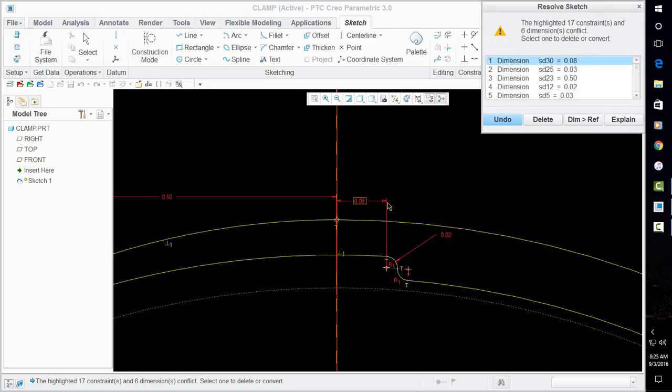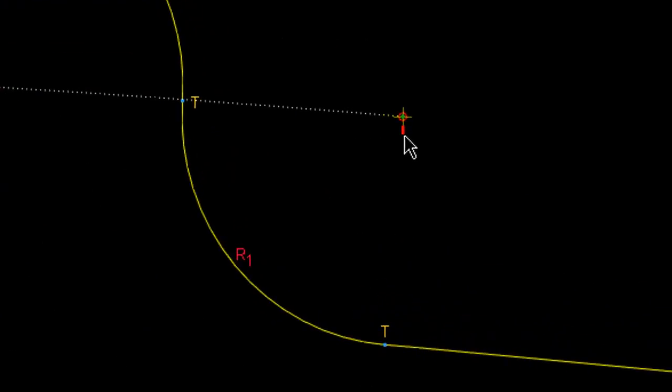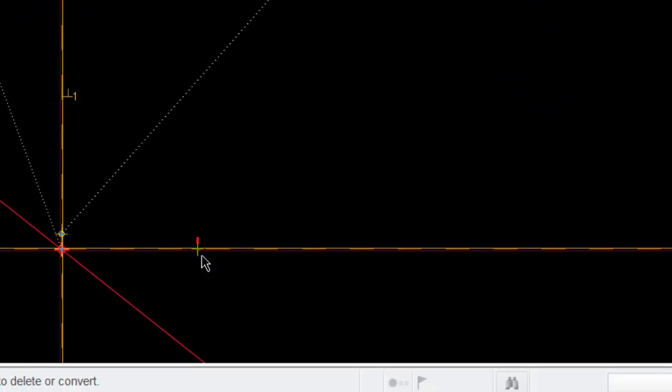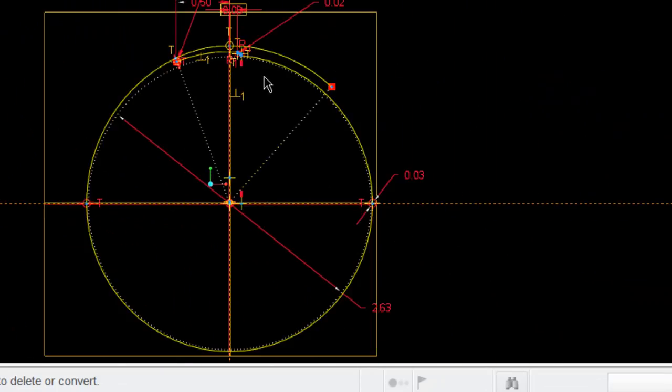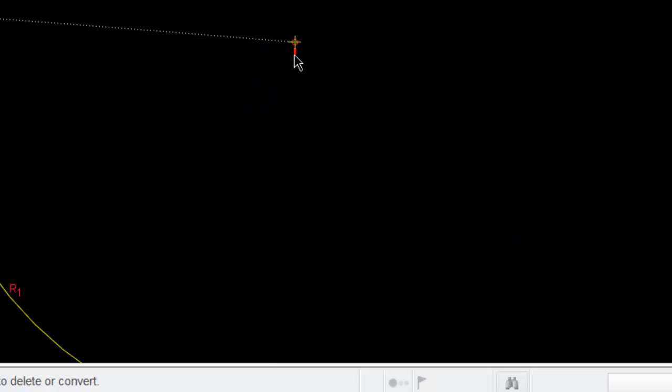And it's saying that something, oh, look at this one. You see this one right here? I didn't notice that one being created. And that's lining up to the center here. That is one I did not want. I didn't even see it, and that's what I mean. Be careful about these sort of constraints automatically happening and you're not catching them. I didn't catch this one.